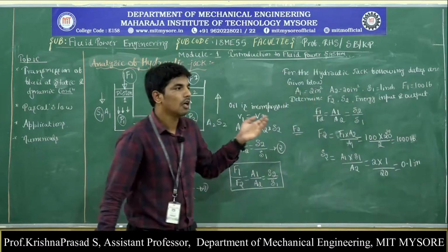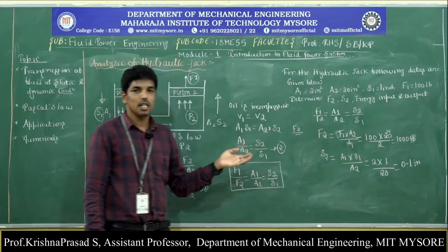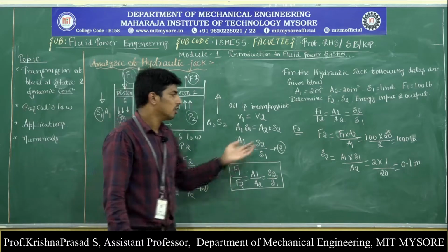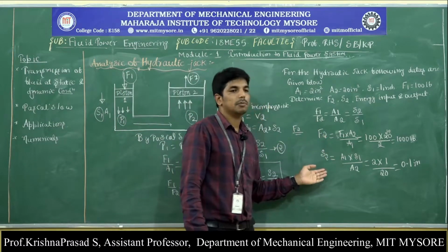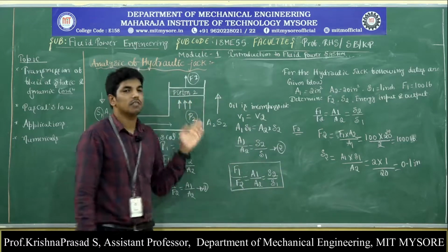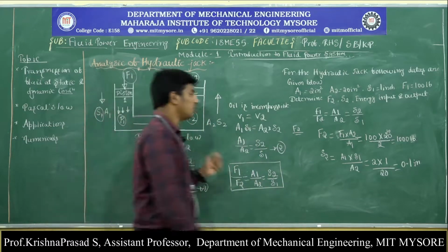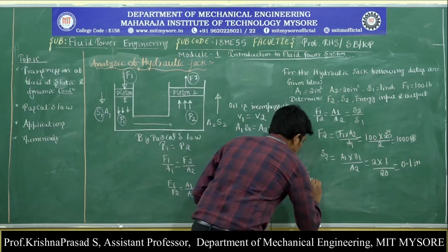So by the application of Pascal's law and the analysis of the hydraulic jack, we have now calculated the force developed and the displacement of the piston in cylinder 2. Next I need to find out the energy input.